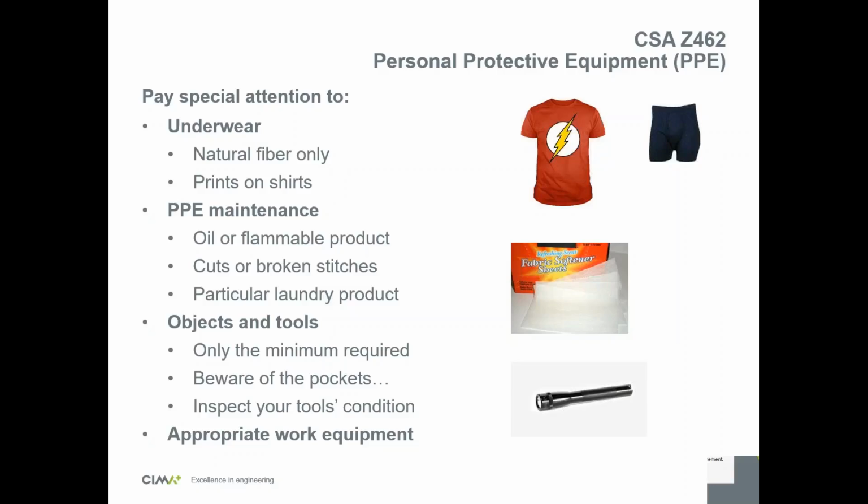And also for objects and tools, make sure you only use the minimum tools required for the job to reduce the risks. Beware of what's in your pockets so it doesn't fall off or anything, and you need to inspect your tools conditions. Also, always use appropriate work equipment. Use insulated tools whenever possible.